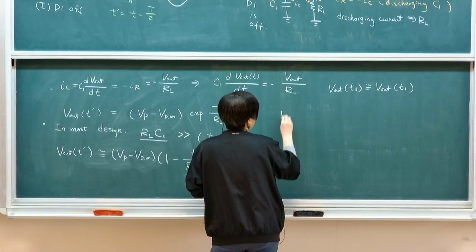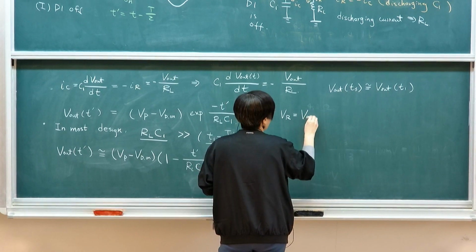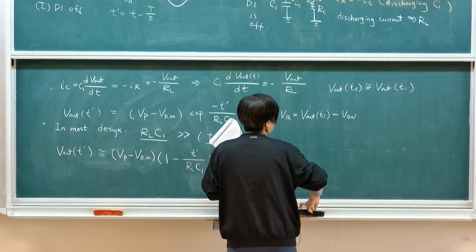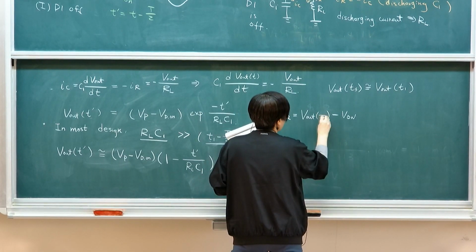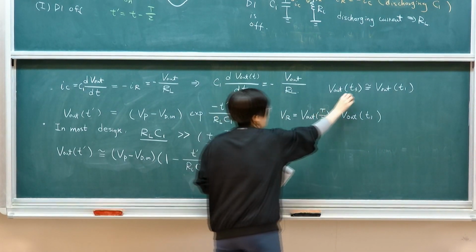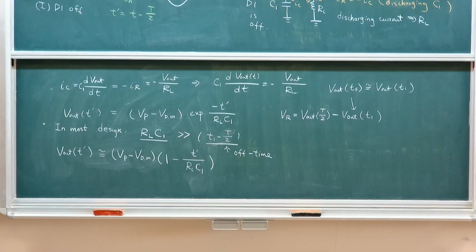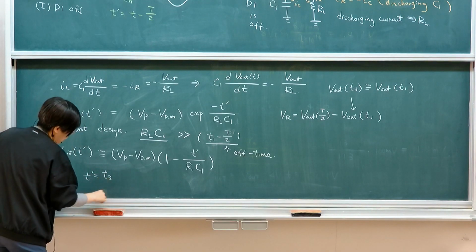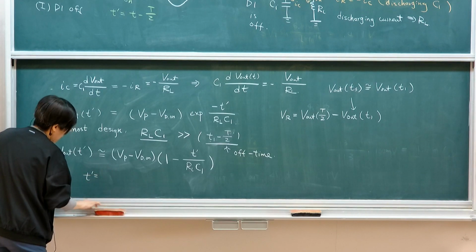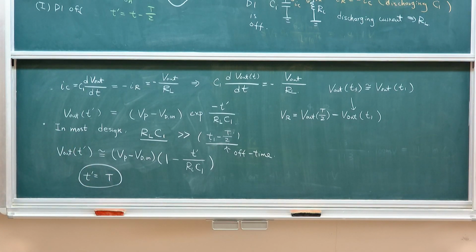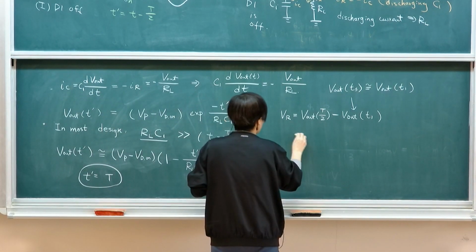So then the ripple voltage is defined as VL at the peak level, minus V out at T1. And I'm using this to substitute. So at T3, actually T prime, at T3 is actually a full cycle. If you think about it, T3 in scale of T prime is a full cycle. So I'm simply inserting that in. So this will be my peak level.